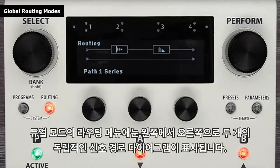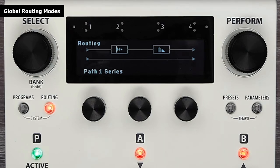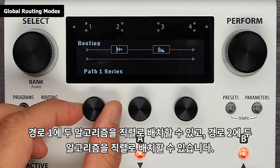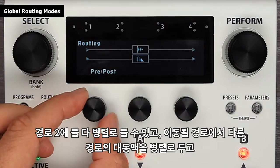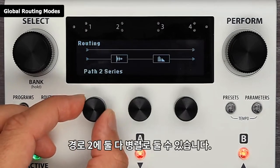The routing menu in dual mode shows us two independent signal path diagrams from left to right. The icons inside of rectangles represent each algorithm of the program. By turning the first quick knob, we can position the algorithms in 5 different positions. We can have both algorithms in series on path 1, both algorithms in parallel on path 1, an algorithm on each path, both in parallel on path 2, or both in series on path 2.